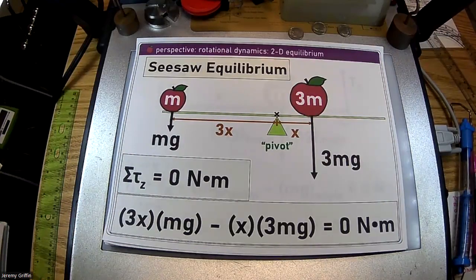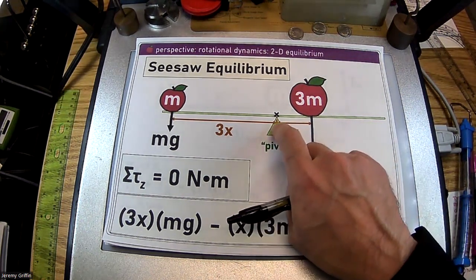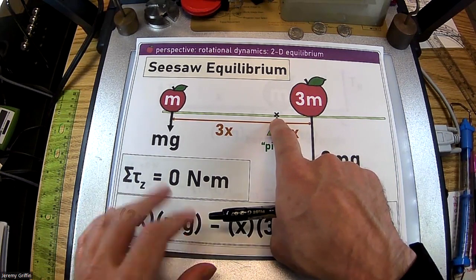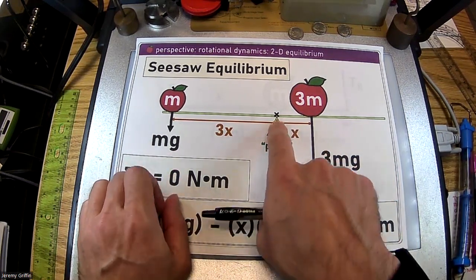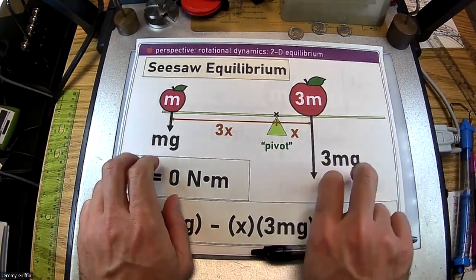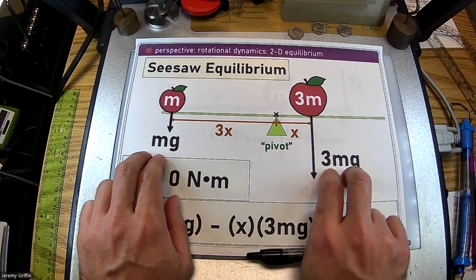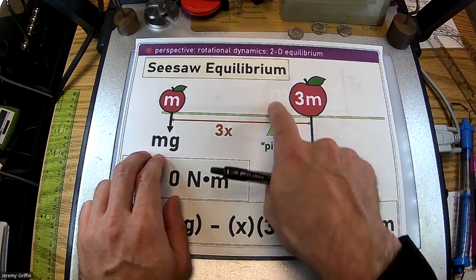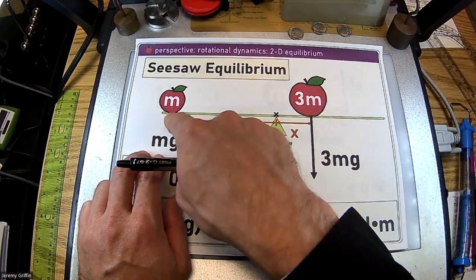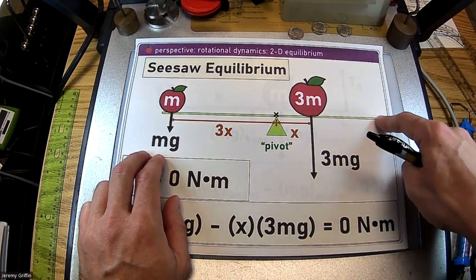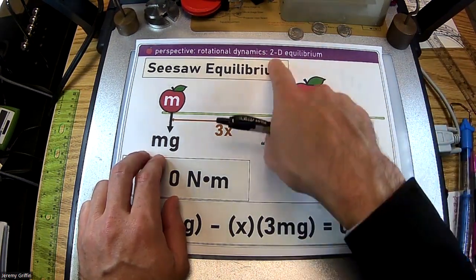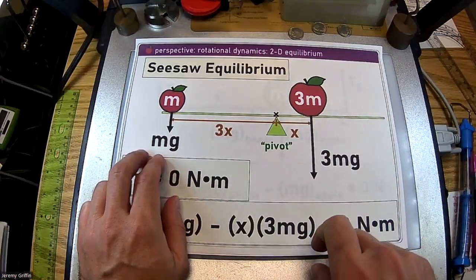Kind of like if I press on the door hinges. Here I'm pressing on the door hinges. Is this ever going to turn the door? No, because there's no turning moment. There's no lever arm. Sometimes it's good to set up a problem like that where you zero out some unknown force. You'll see something like that pretty soon. Do you think this upward force has to be at least 4 mg to carry all this weight? It would be just 4 mg if the mass of the plank itself was negligible. If you include that weight also, it's probably a little bit more than that.